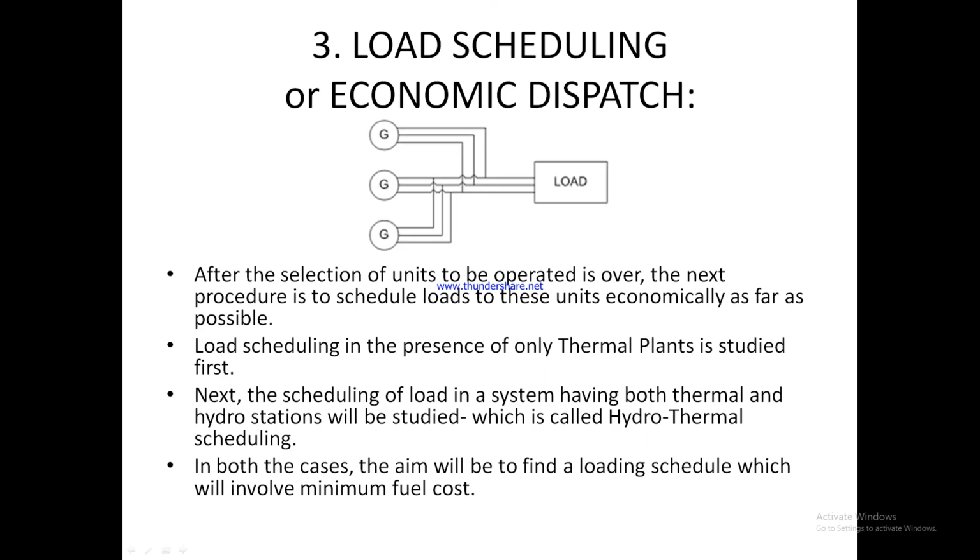3. Load scheduling or economic dispatch. After the selection of units to be operated is over, the next procedure is to schedule loads to these units economically as far as possible. Load scheduling in the presence of only thermal plants is studied first. Next, the scheduling of load in a system having both thermal and hydro stations will be studied, which is called hydrothermal scheduling. In both cases, the aim will be to find a loading schedule which will involve minimum fuel cost.